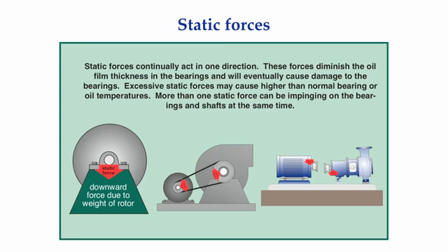Keep in mind that the bearings on the motor and fan are seeing forces from two different mechanisms on belt-driven machinery. Not only are the bearings seeing the downward force due to the weight of their shafts, but now an additional force from belt tension is present. Another classic example of a situation that will produce static forces on bearings is a shaft misalignment condition.